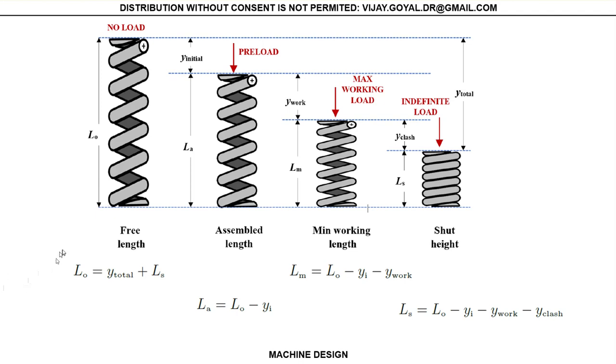And just note that everything we are doing, we are talking about linear springs, not a nonlinear spring. So if I'm saying I have y initial, well, that's also going to be related to some F minimum or F initial, and we have a slope k. This is load, and this is your displacement. So this is known in the problem. These curves are typically known from the problem for every spring, and they come from test data.